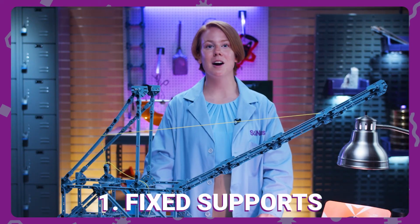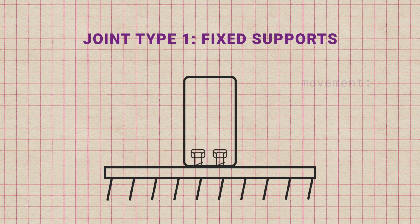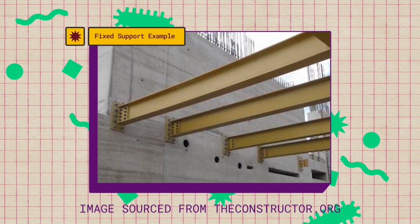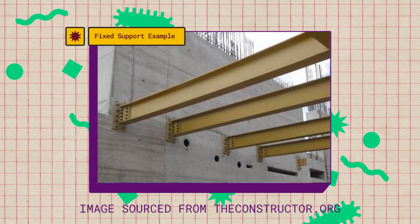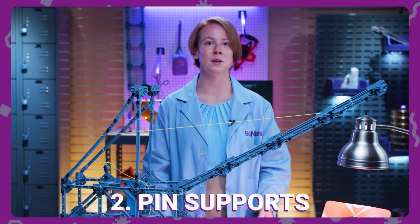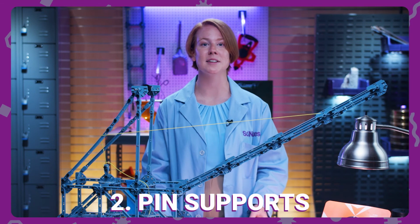The first type are fixed supports. Fixed supports are meant to join 2 members but not allow any movement, whether it's up, down, side to side, or rotation. Fixed supports can be surrounded by bolts, triangular plates, and welded to keep the structure from moving. The second type are pin supports, which are a step down from fixed supports when considering how much movement is allowed.